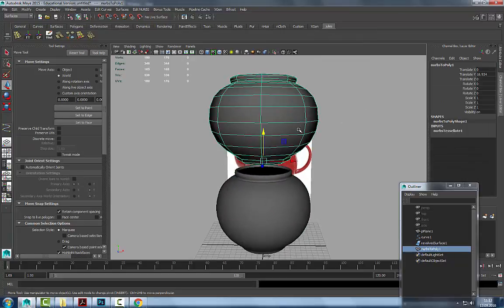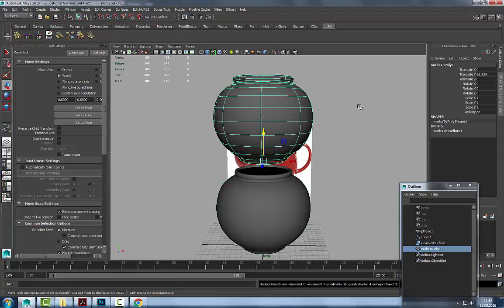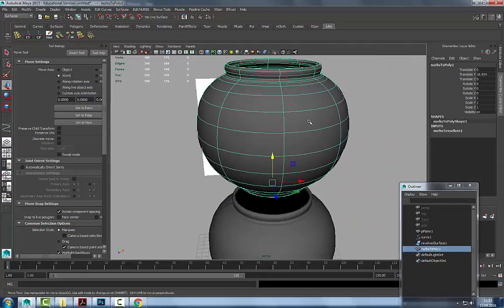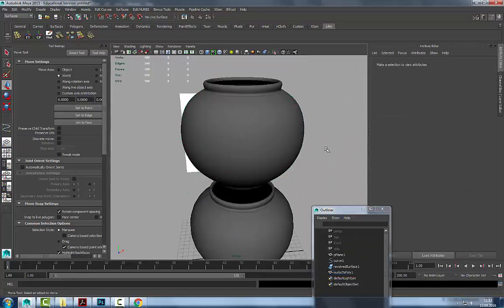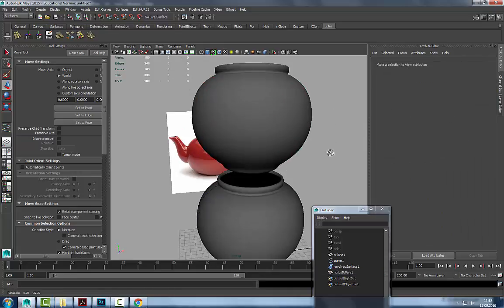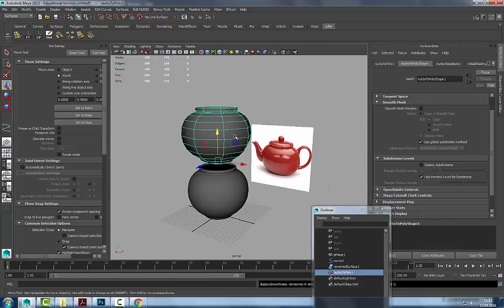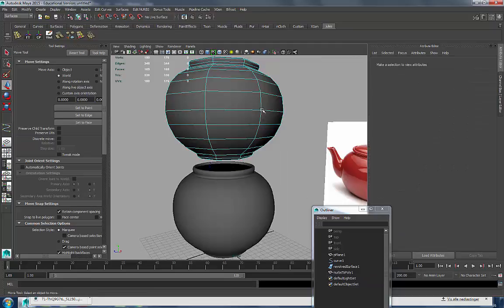Now, you might say that looks ugly compared to this beautiful curved surface, but then you can subdivide this and you won't be able to discern the difference, especially if we go into the attribute and set a higher preview. Now it's subdividing these a ridiculous amount. We can toggle between them, the benefit being that we can still alter the mesh, like doing extrusions.